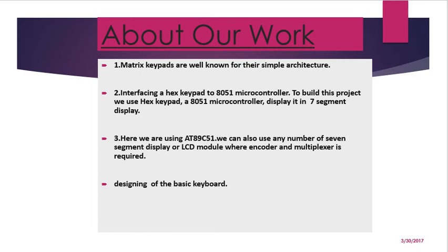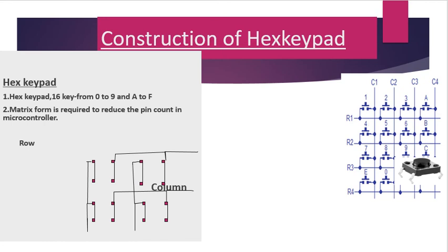Designing and construction of a hex keypad. A hex keypad has 16 keys, from 0 to 9 and A to F. Matrix form is required to reduce the pin count on the microcontroller. Here we show the circuit diagram of the hex keypad.